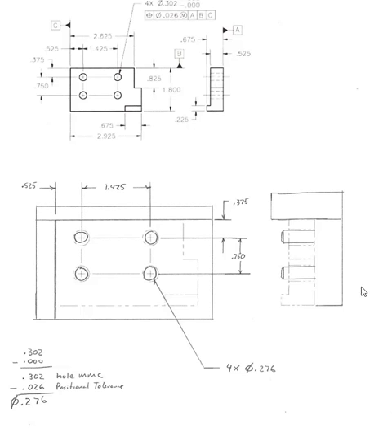So what I do is I create this gauge. This functional gauge simulates datum A here. The part will sit on it, and the functional gauge also simulates datum B with this piece here, and it simulates datum C with this piece here. And it has 4 pins, and these 4 pins are designed to go clear through the part at the virtual condition of the part.